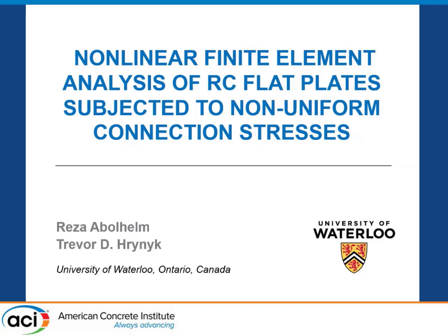And specifically, he was doing some finite element simulations to assess the applicability of an existing modeling method for certain types of punching-related analysis conditions we hadn't looked at before. We've named this RC flat plates subjected to non-uniform connection stresses, which you can make a case they're always subjected to non-uniform connection stresses. But here we're talking about non-idealized slab-column connections that really accentuate eccentricity or having very large shear stresses on one side of the column or something like that, other than bending. Okay, so just due to gravity loading.